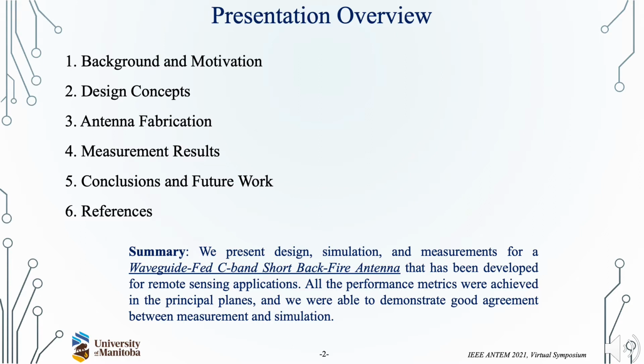In summary, we present design, simulation, and measurements for a waveguide fed C-band short backfire antenna that has been developed for remote sensing applications. All the performance metrics were achieved in the principal planes, and we were able to demonstrate good agreement between measurement and simulation.